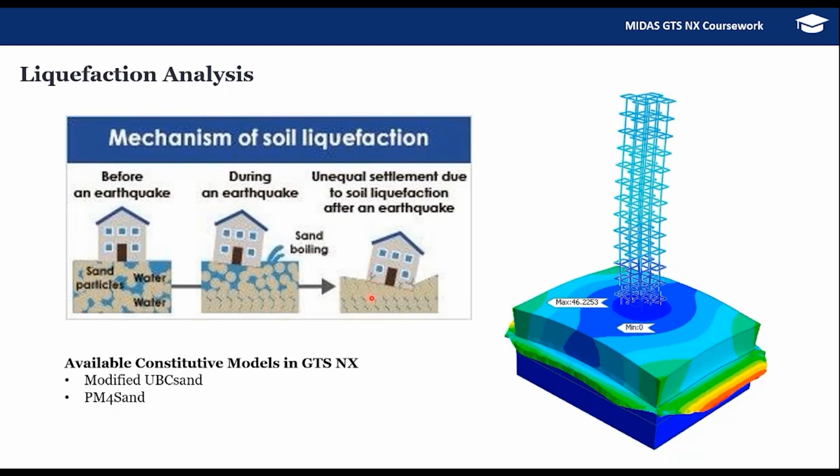But an important thing in order to avoid liquefaction is a proper pile foundation. A pile foundation is the best technique for liquefaction. That's another scenario altogether, another topic. But in order to simulate liquefaction analysis, we have two material models in GTS NX. We have modified UBC sand, and we also have PM4 sand materials. Using these materials, you can simulate the liquefaction analysis.